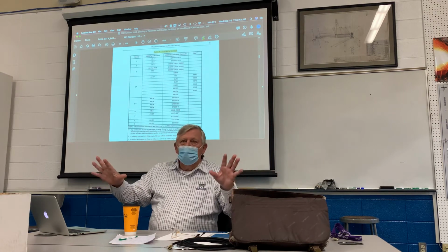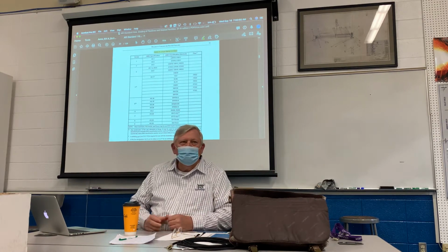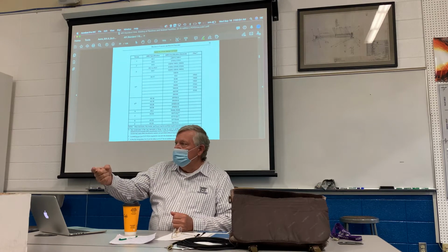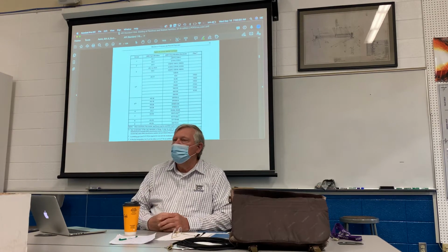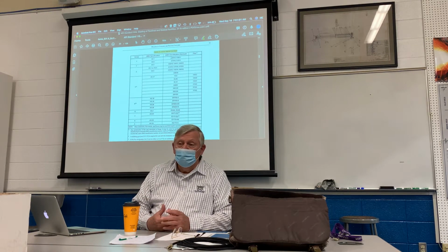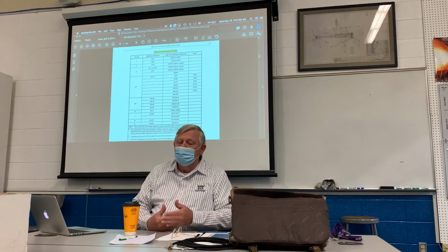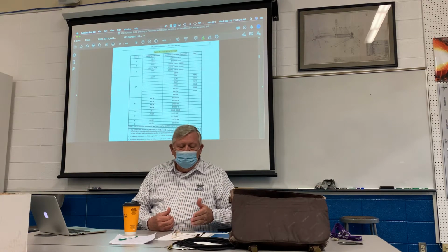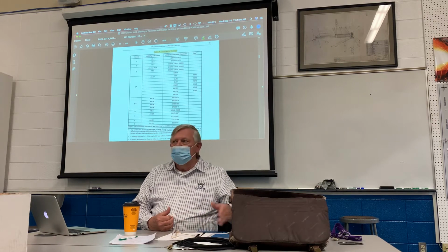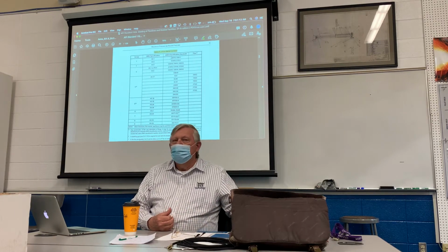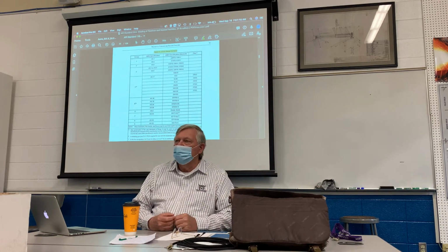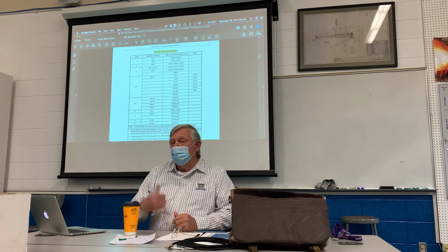So people call it farmer rod. That's where they get the farmer rod. But that 6011 allows you to use it in AC. But the crazy thing about the 6011 now, you can get a DC version because they found out the electrode was much stronger, especially in the case in the not as welded form. But if you make a pass with 6011, then you put another pass over the top of it, it anneals the first pass, and the tensile strength goes to about 85,000. So that's why it's still in there.